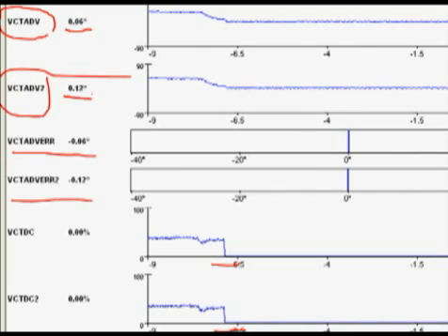First of all, this particular PID displays as a histogram, so that blue bar indicates what is happening at the far right-hand edge of the capture. Same goes with the digital readouts on the IDS capture. So whatever is current is what's being displayed on the digital readouts and on those blue bars. And as we can see, everything's working properly right now.